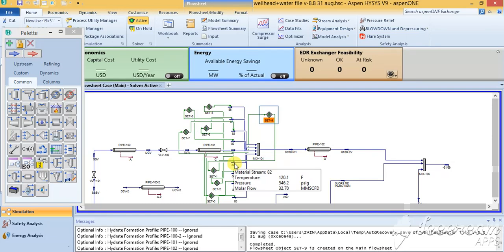Then there is an adjuster. For example, if you have a smaller amount of gas or oil that is not matching up with the PVT sim data that they have given you, through the different flash systems, multi-stage flash system or single stage flash system, sorry, I put the wrong wording. It is not single phase or multi-phase, it is actually multi-stage or single stage. As we define in the single stage that this much amount of gas should be recovered through the flashing, you can also adjust that through this adjuster icon.